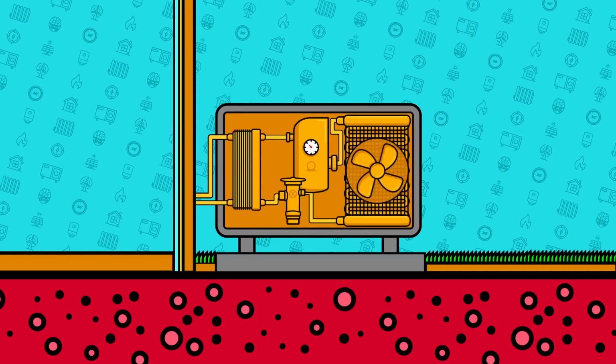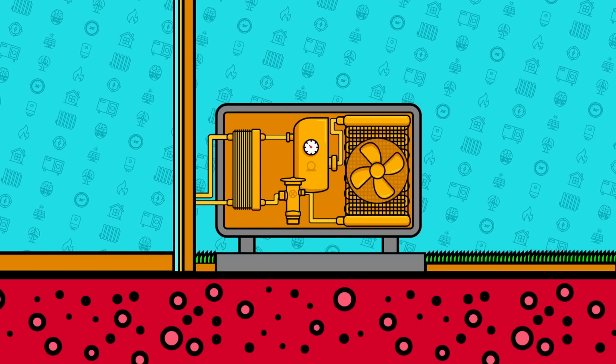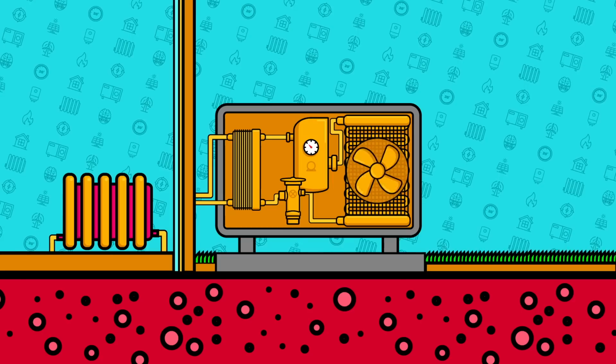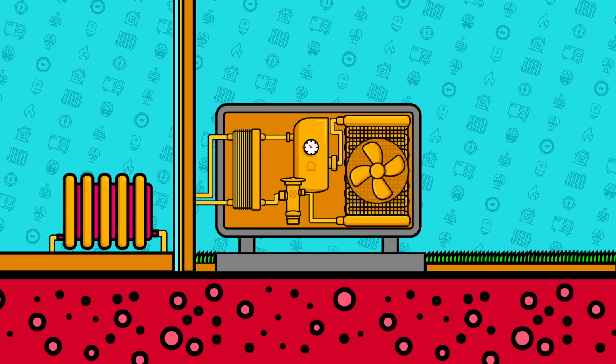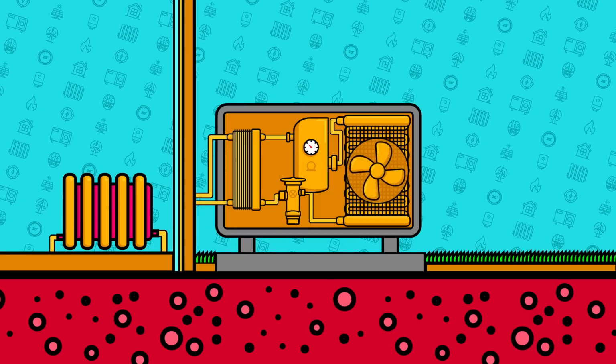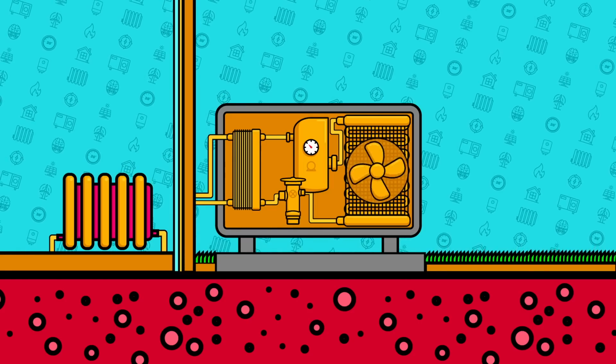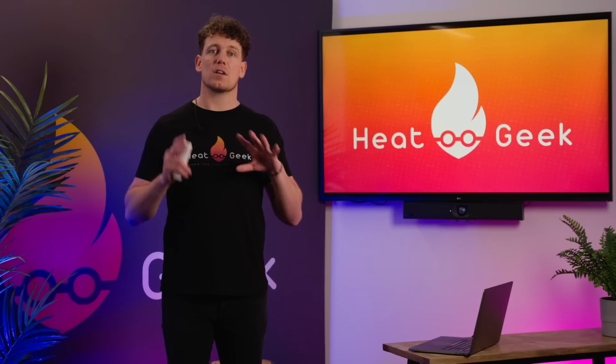A monoblock system is becoming the unit of choice for air source heat pumps connected to radiators and underfloor heating. These have both condenser and evaporator elements outside and sometimes incorporate a system pump as well. Because these don't have custom-built fridge lines going into the house, they don't need to be filled by a fridge technician, and so save time, cost, and risk.